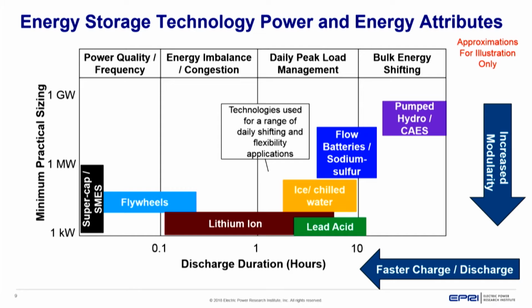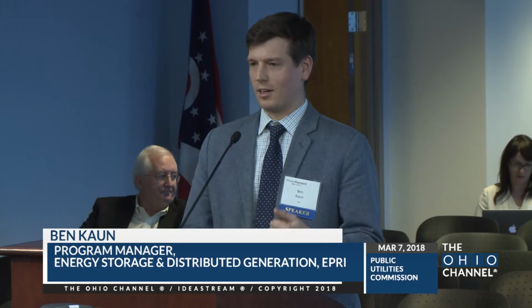And if you look at the size of the technology of these different batteries or thermal technologies, some of them make sense. They're modular enough to be individual cells. You can build them into very small packages, like obviously lithium-ion can be in your pocket. So there's very small cell capability there. On the other hand, in the blue space here, flow batteries or sodium sulfur are not quite as modular. They're semi-modular, but not something you're going to put in your pocket. One of the other things I want to point out about this slide is that lithium-ion has been a very attractive technology in part because of a very wide range of potential discharge durations, from a few minutes to charge and discharge the full lithium-ion system up to several hours. So it really covers a lot of the sweet spot of what's currently being looked at as needs for the grid.